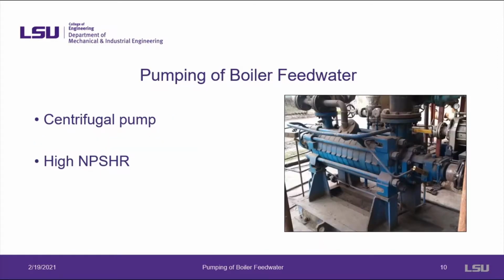Centrifugal pumps are universally used to send boiler feed water from the deaerator to the boiler. Here, it is important that the demineralization process was effective in order to avoid pressure drops in the line between the deaerator and the boiler. The pressure drops would be due to mineral deposits on the inside of the pipe.